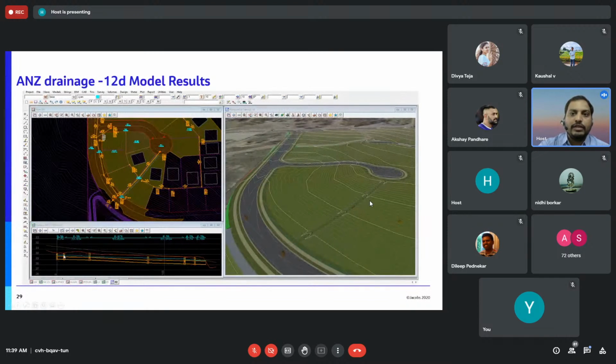Below that you can see one L section, where you can see the pipe having the invert levels, you can see 29, 30 here. These are the invert levels. Above you can see the length, and above you can see the slope, which is normally maintained at 0.5%. And we are going to discharge at an outfall location, where you can see some small ditch type ground, where we can have a safe